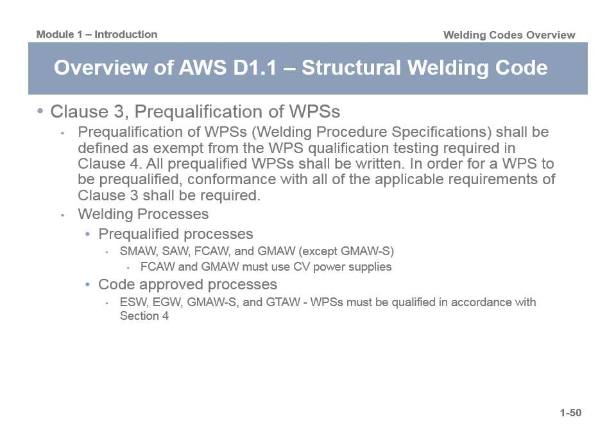You can use this filler material with this base metal and this welding process, and if you follow everything else that is written in clause 3, all the requirements, it's pre-qualified. You don't have to qualify the welding procedure. It's just pre-qualified. So if it falls outside of that, then you have to use clause 4, and you actually have to do a PQR and a WPS for that particular weld procedure.